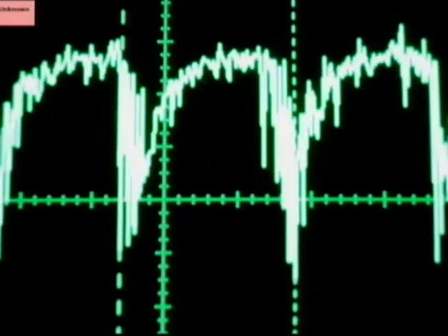This is a recording of the power consumption of a chip. Once you capture a wireless sensor, you can knock the decoupling capacitor off of it. And I'm sure you've seen the side-channel power analysis attacks against smart cards. But this works differently in that you're not really trying to figure out what it's computing, so long as when it's computing it. Because if you want to glitch, you want to do it on one of these falling edges, which are the moments at which a clock edge occurs. Because on a clock edge, a CMOS transistor will flip. And it's only when a transistor is flipping in CMOS that it consumes power.